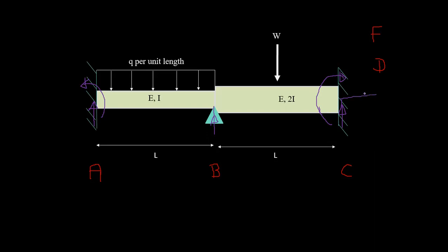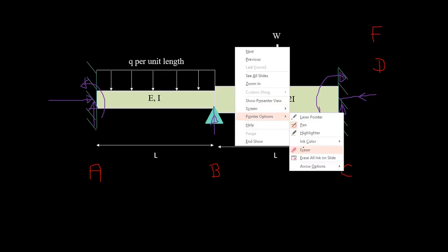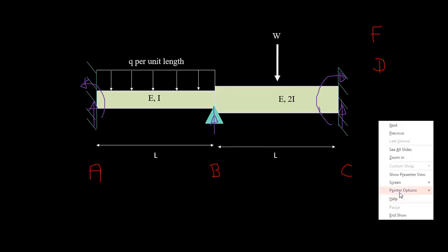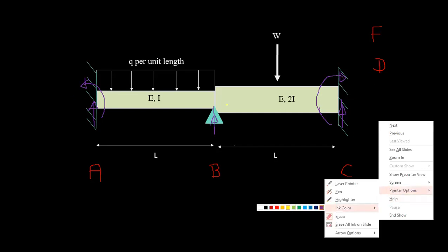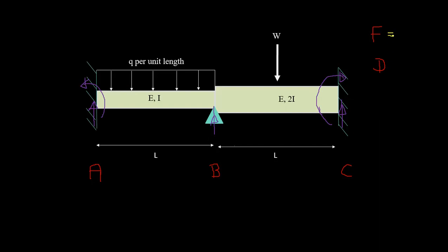If you want, you can consider these, okay, right? No problem, because there's no horizontal axial loading, right? So that's why I don't need to consider those for now. If you have some axial loading, definitely you need to consider that. So you already have 5 unknowns, right? 5 unknowns, and you have 2 equations, the vertical force equilibrium and the bending moment equation. And you can't use the horizontal reaction equations as well. So that means you need to solve for 3 redundants. There are 3 redundants, right? So that means you need 3 additional equations.